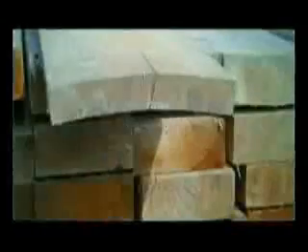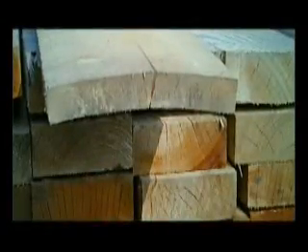Loads are normally cooled down to a temperature safe for workers before the chamber is unloaded. The faster the cool down period, the less wood drying and degrade that occurs, and the faster the next cycle can begin. Cool down can occur by manually opening doors and vents, which requires workers to stay on top of the operation, by opening vents automatically, or by letting the closed chamber sit long enough to cool down.